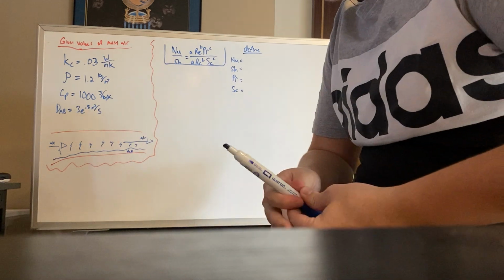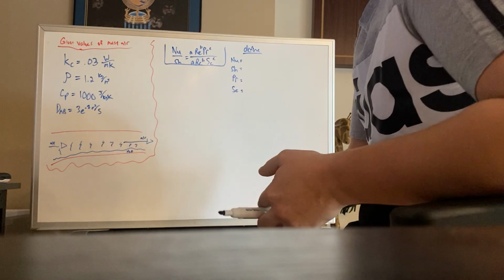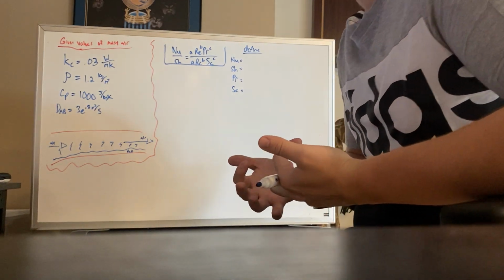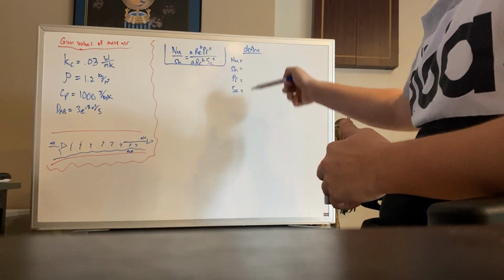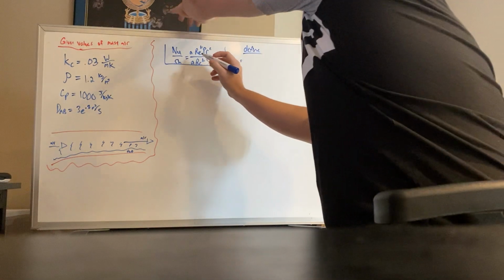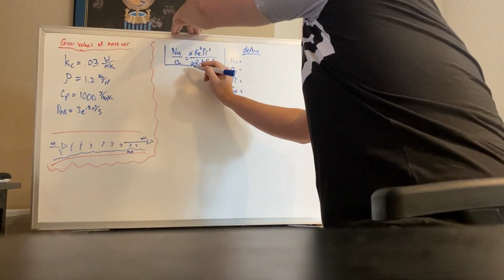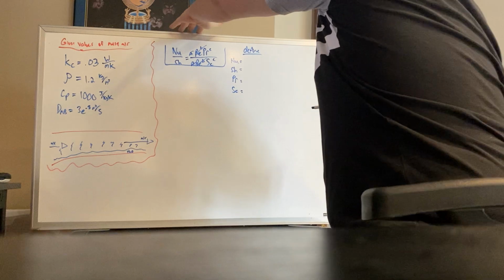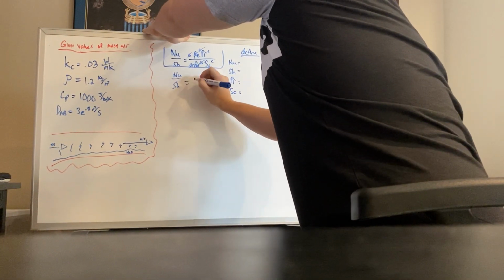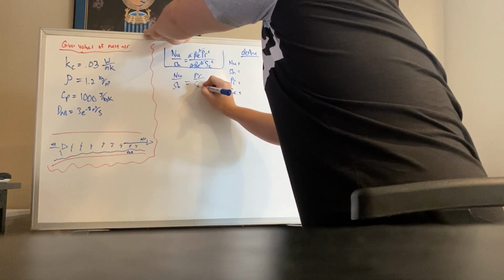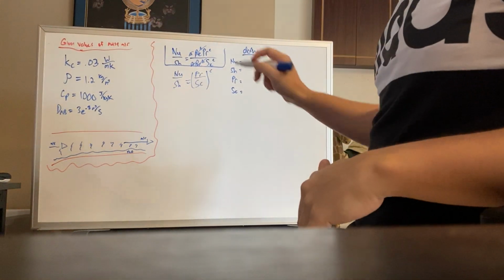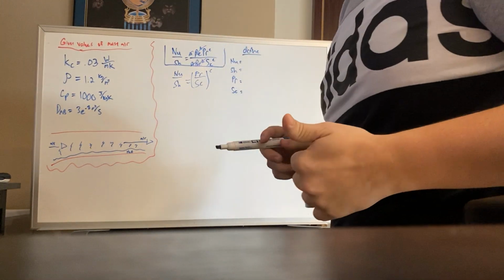And so the first thing that we really should do if we're going to try to understand the Lewis relationship is work our way to getting to it. So we're going to have to go through and redefine Nusselt number, Sherwood number, Prandtl number, and Schmidt number. This is because if we're looking at this equation here, the A's cancel out and the Reynolds number to the power of B's cancel out. So really we're left with Nusselt number over Sherwood number equals Prandtl over Schmidt to the power of C. So that's what we're currently dealing with, since those do cancel out.